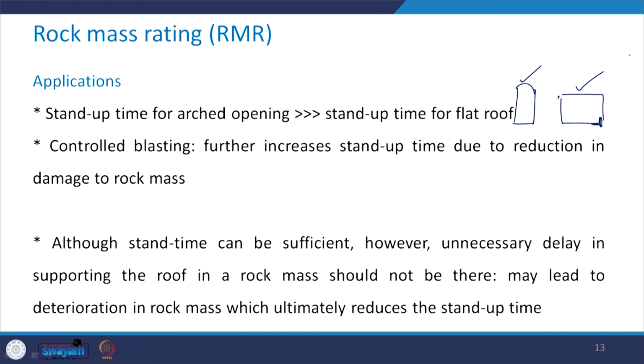So, the stand up time is going to be larger for this case as compared to this case. Now, if for the excavation you are going for controlled blasting, that further enhances the stand up time, because with controlled blasting there is a reduction in the damage to the rock mass and therefore the stand up time increases.